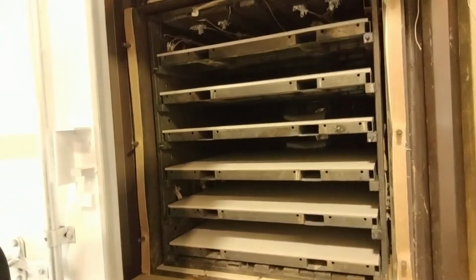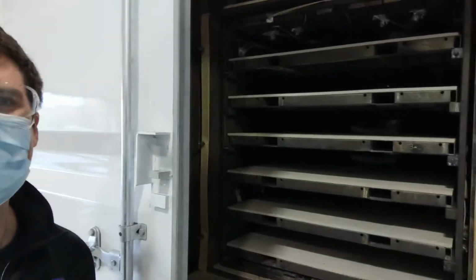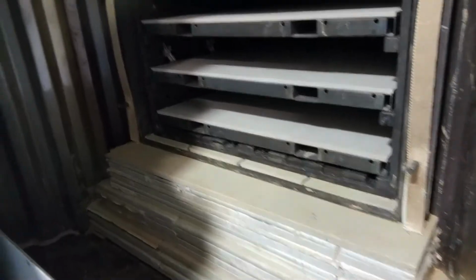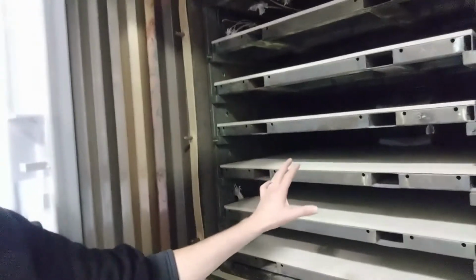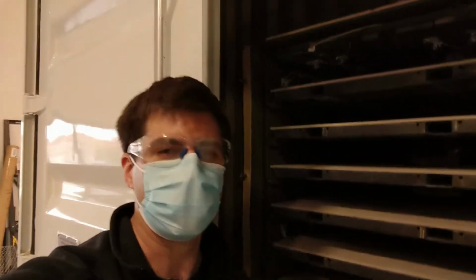Again, this is what we use to operate and demonstrate self-heated operation with R&D cells. You can see here is a container that has a rack inside of it with 6 trays that can get loaded with cells. Cells are electrically isolated from each other and then linked together through series connection. The boards underneath are thermal insulation. And this whole cavity here is filled with patterned thermal insulation that allows the inside of this container to stay at 500 degrees Celsius, and the outside of the container is cool to the touch.